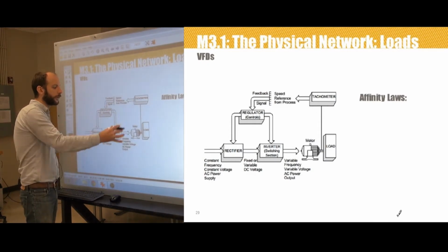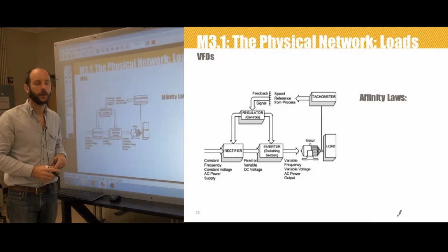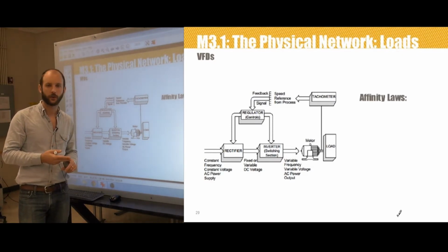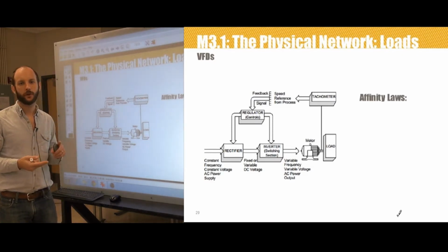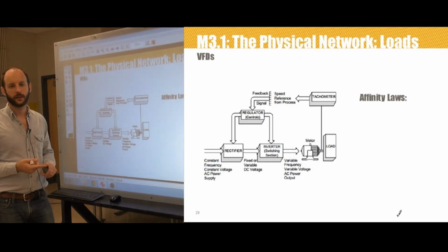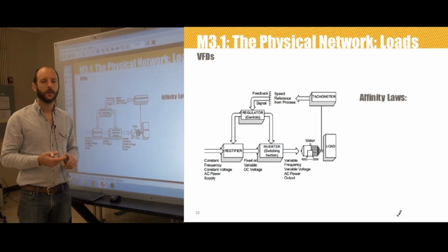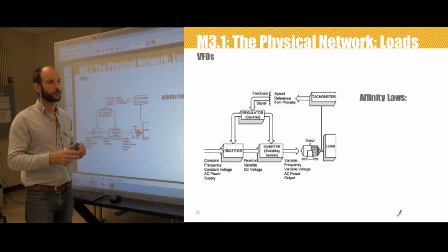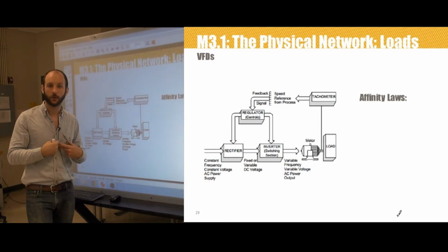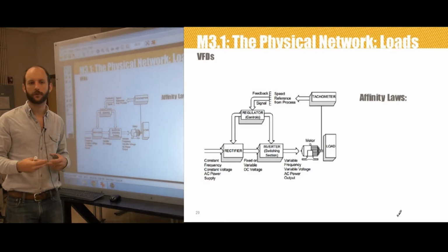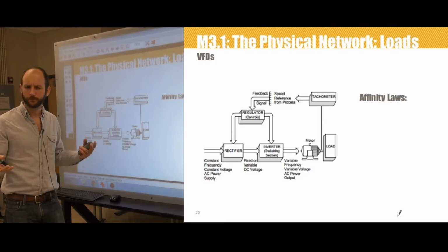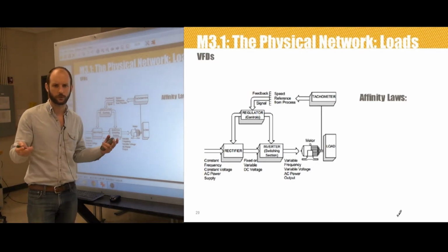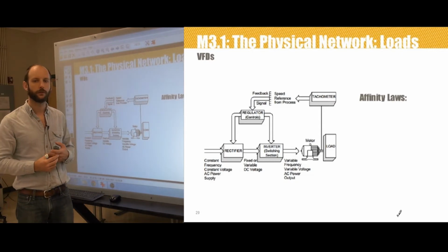So let's look at this device, the variable frequency drive, in a little bit more detail. It really has two stages of power conversion, like I said earlier. It's got the first stage, which is a rectifier, and the second stage, which is an inverter. And somewhat confusingly, the term inverter is commonly used to refer to the entire drive. I don't do that personally. I call it a variable frequency drive, or a VFD, but for some reason, colloquially, inverter is a lot of times used to describe a variable frequency drive.